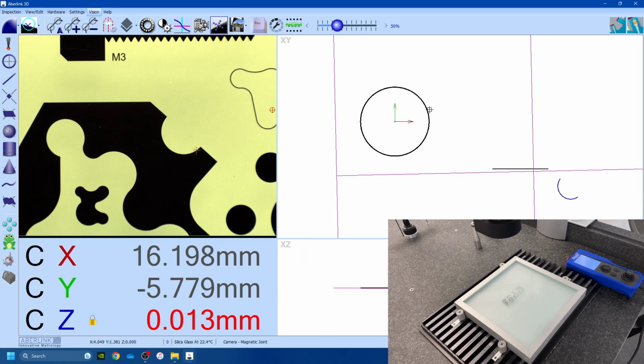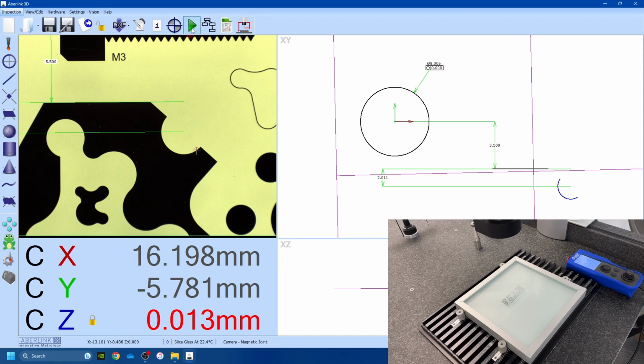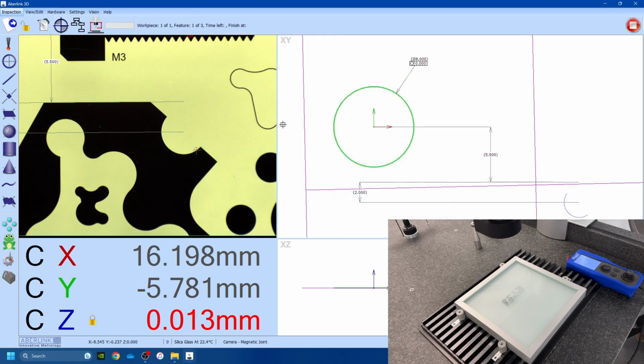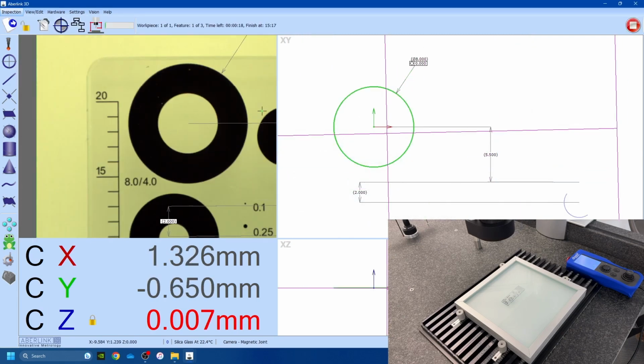And if this was being used as a program, and again, just to stress the point, this is used when the camera struggles to get the edge of the component, but you can visually see it by eye. You can use Smart Mouse to create a repeatable program, picking up on the edges by eye rather than using the edge detection. And the reason we use Smart Mouse is if we play this program back, the software drives over and gives us a target point to try and measure.